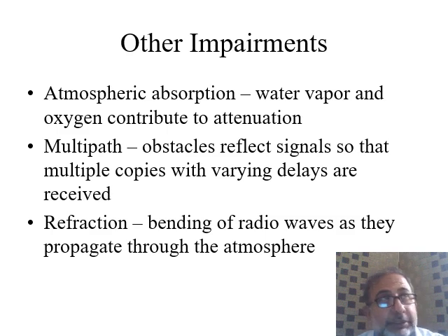Now it is up to the receiver to either add them up by giving intentional delays to the early coming signals and adding them all up, or the other thing that can be done is that it can select the most powerful signals and reject the weaker signals.